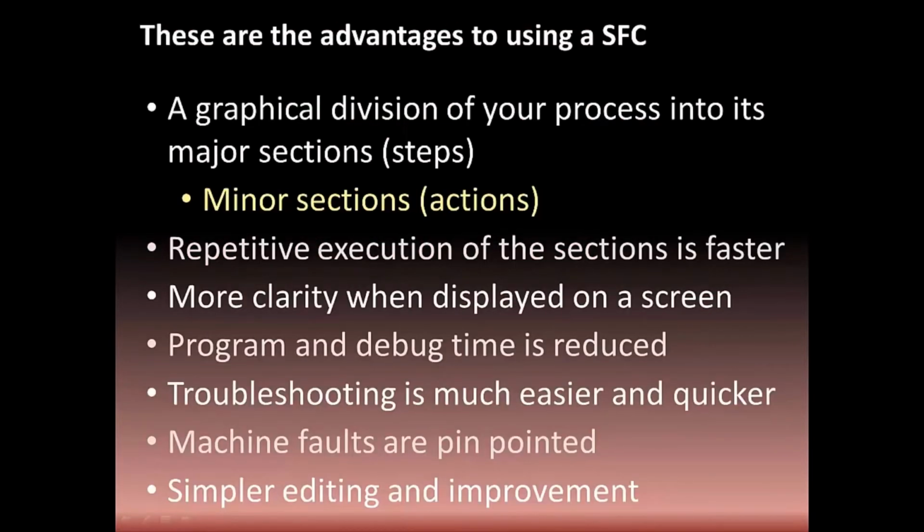Some additional advantages of using a sequential function chart. Now, I would like to reiterate that if you have to struggle to create a sequential function chart for your process, then your process probably does not need a sequential function chart. Some processes are too simplistic. However, some processes really come to life with a sequential function chart. A sequential function chart allows you a graphical division of your process into its major sections.